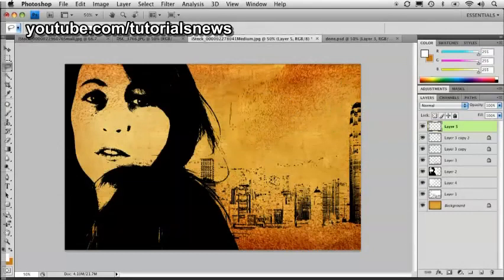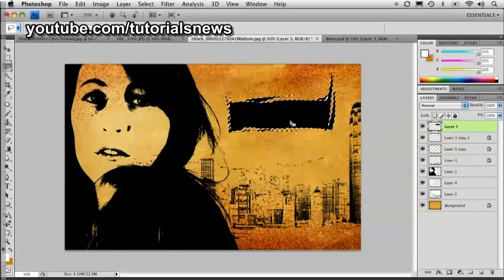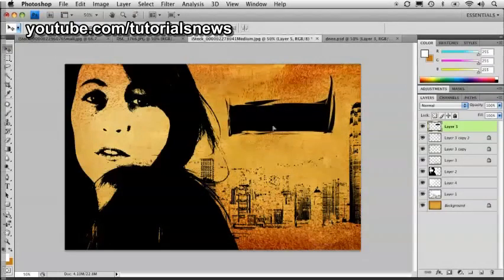Starting right here, I'm just going to zigzag around, keeping in mind the shape that I'm trying to achieve, which is a square. And we'll come right back to where we were. Maybe one little swoop out there, and there we go. So there's a selection. On a blank layer, I'm just going to hit Shift-Delete, so bring up the fill here, and we're going to use black. Click OK. I'm going to press Command or Control D to deselect, and there is our shape that we've created.